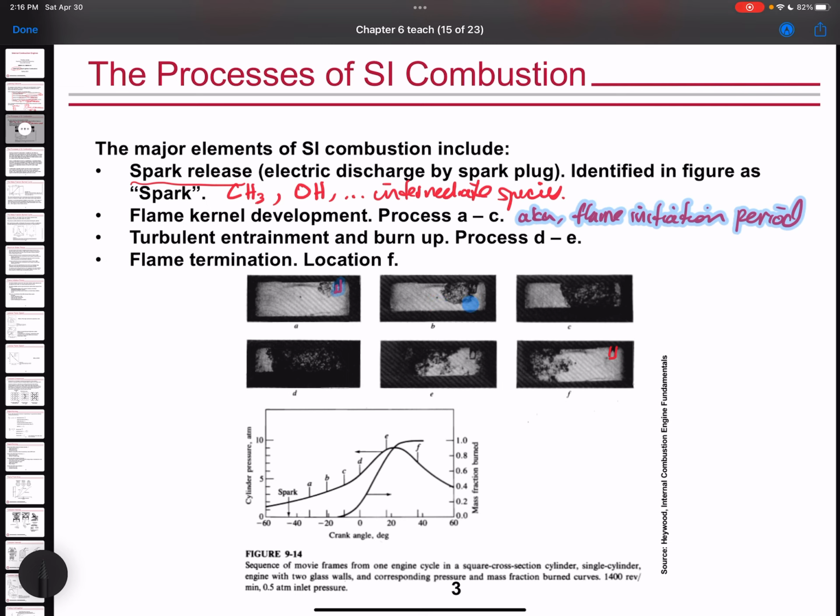So by it getting a little darker, that's indicative of the fact that the density gradient is getting stronger, right? In other words, the density of this portion of the mixture is further departing from the density of the rest of the mixture, where, of course, we don't see any gradation in these other portions of the mixture at all. And then finally, we move to image C. And in image C, the area where there's a gradient difference has grown larger and gotten much darker, okay? That's basically the point where you would begin to see a visible flame during the combustion process, right?